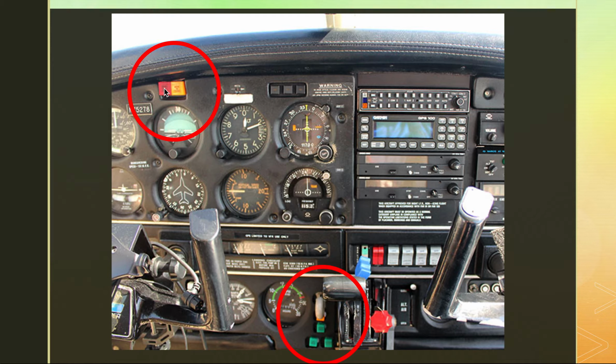So, for example, if you take off, positive rate of climb, no runway remaining, you put the landing gear handle up, it takes like 5 to 8 seconds for the gear to retract. So for 5 to 8 seconds, it's not safe because it's not up or down. And then you'll feel it thump into the airframe, the gear unsafe light goes out, and you look down and see a gear up indication on the yellow or amber light.